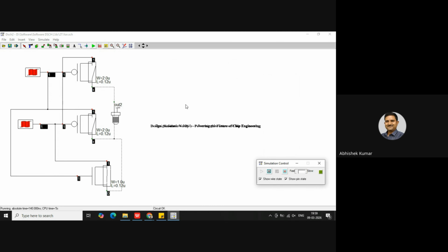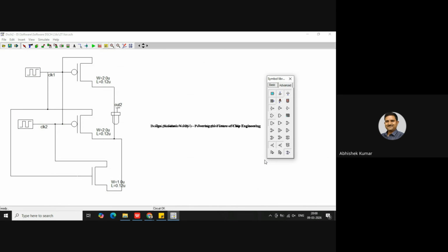Okay, so in this case it is defined as an XOR gate, whose equation is A bar B plus A B bar. I would need at least 14 logic gates, NMOS and PMOS. But here, with the sizing of W, I put the PMOS at 2W and the NMOS at 1W, and this type of connection represents the PTL logic, pass transistor logic.